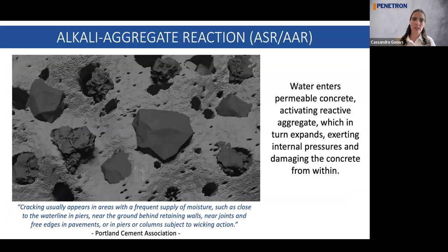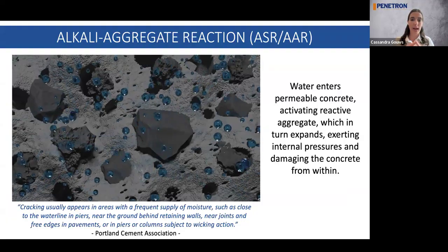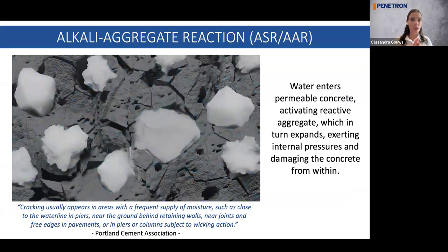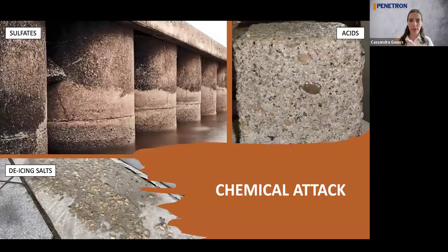The third deterioration factor is due to alkali aggregate reactions, known as ASR or AAR. Now, when your aggregates in certain areas are reactive to the cement paste, it forms like a microscopic gel layer around the aggregate. Now, that gel layer is not bad, but as soon as water touches that gel layer, the gel expands, causing internal pressures, causing your concrete to crack and spoil. And then we get more water, and then we get to corrosion of your embedded steel. So overall, not good for the concrete.